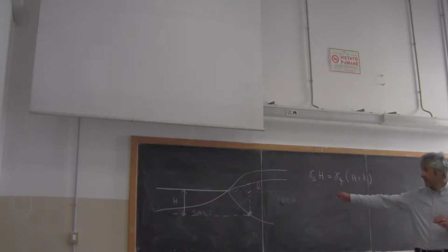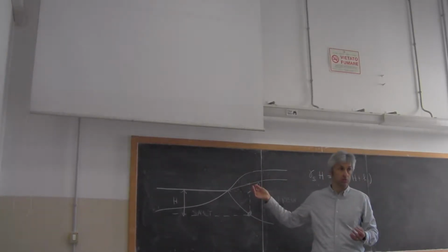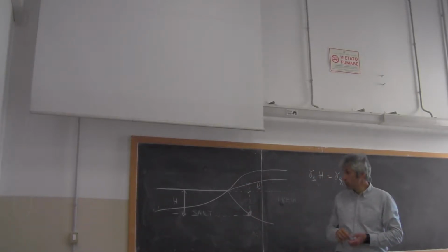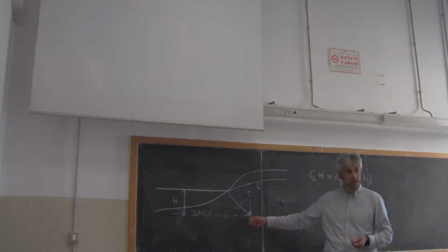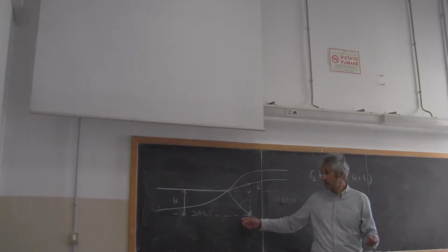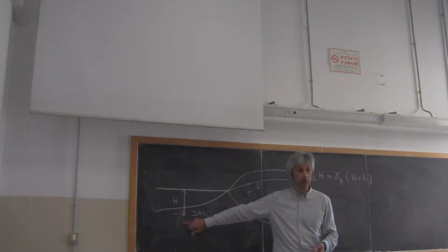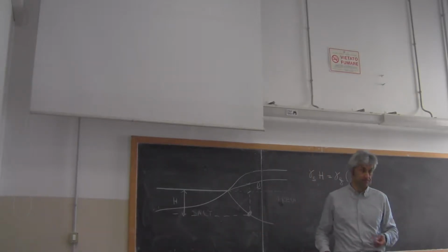Keep in mind that gamma S is higher than gamma F. This is why you need a higher column of fresh water in order to push salt water back, in order to keep equilibrium here, in order to balance the pressure of salt water given by the water column capital H.